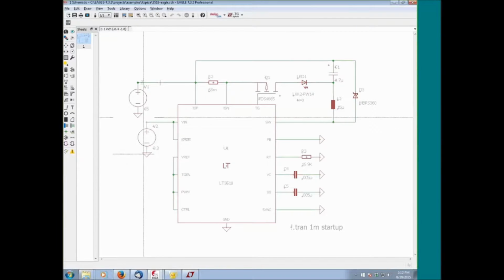These are simulation sources. Normally you would have some sort of linear regulator, or the reality would be a linear regulator or switch mode regulator. This brings us to a first key point about simulation. It's generally very difficult to simulate the entirety of a circuit. What you want to focus on is the key points you want to make sure are plausible, or the design elements you're not 100% sure about. That's where you really want to focus your simulation effort. So things like the power rails can be substituted with this simplification, which is a voltage source.